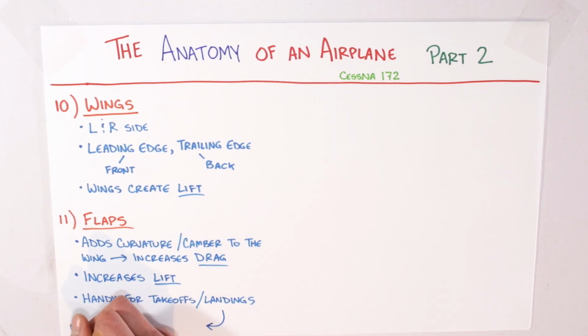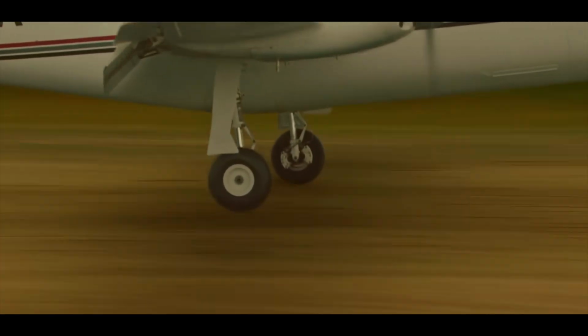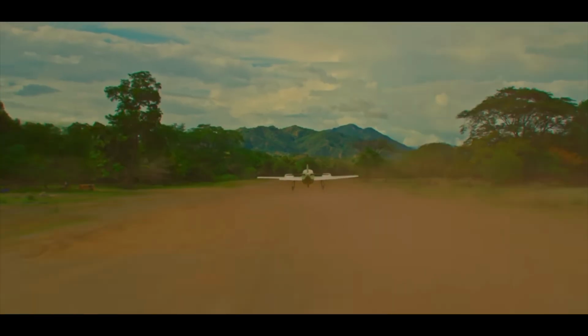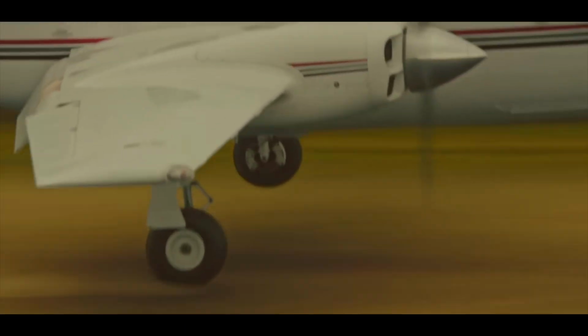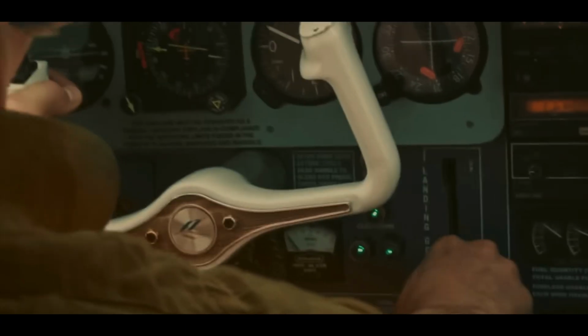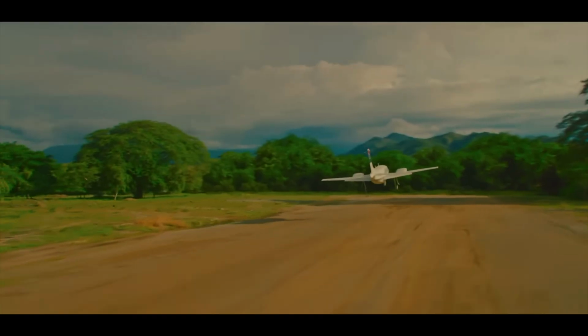Flaps are mainly useful upon takeoff if the plane is taking off from a shorter runway. If the runway is not very long, the pilot is going to want as much time as possible to get airborne because he has less room to work with. Deploying the flaps slightly allows the pilot to lift off at a slower speed, ensuring a safe takeoff.